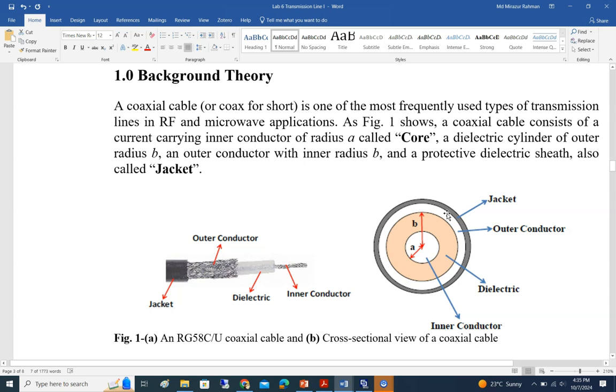This is something called skin effect. It is a very important feature when we are designing any coaxial cable, skin depth, because this conductor carries the electricity. Skin depth determines how the electricity can penetrate through the cross-section area. It is a very important characteristic to determine how the electromagnetic wave will propagate, and whether there will be a lot of loss or not.